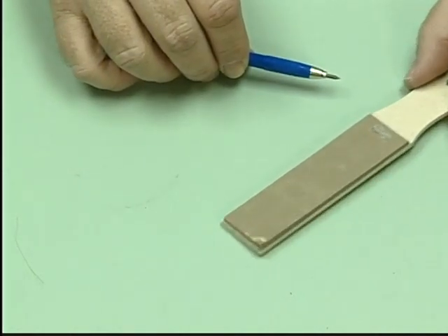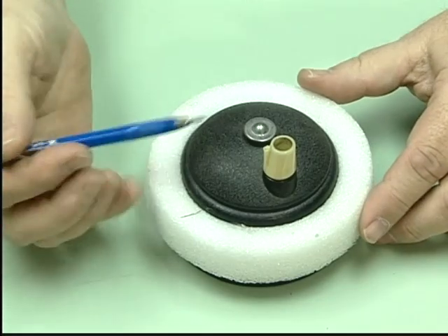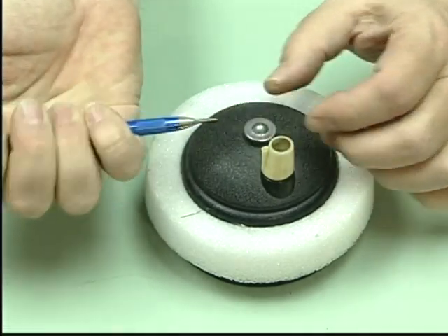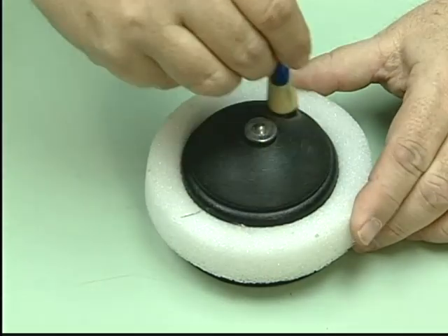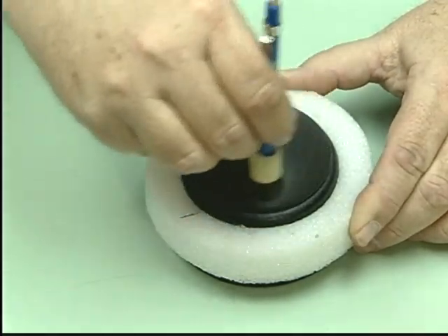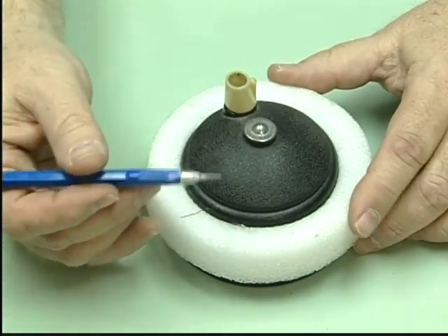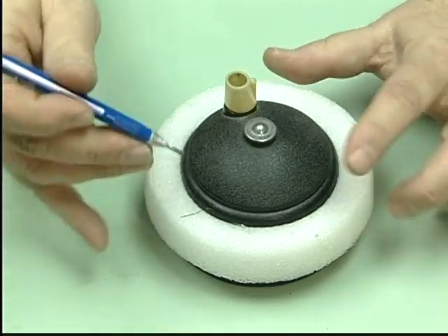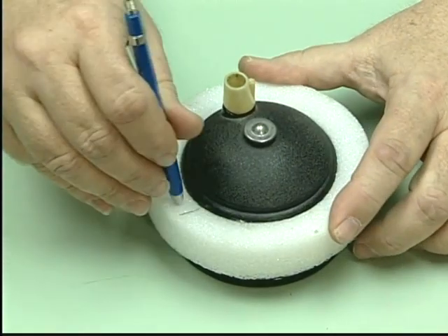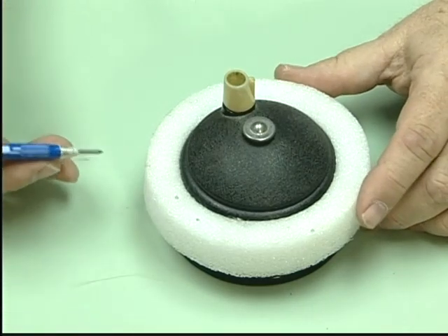More common, you'll see different kinds of pencil pointers. Here's one that we used to call a coffee grinder. What you do is you adjust the lead here until a certain amount is sticking out. You put it in, and inside this device is a cone-shaped piece of sandpaper that as you go around and around will sharpen this to a very nice point. Now when you do that, it'll pick up a little bit of graphite dust, and that'll get on your drawing and make a mess. So we have this little ring of styrofoam here we can poke that lead into and clean all that graphite dust off. You also might use an old art gum eraser for that.